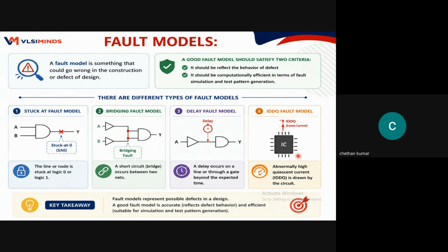IDDQ faults relate to abnormal current being drawn from the circuit; if excess current is drawn, that is related to IDDQ faults. But in our training, as well as in the industry, the main focus is on stuck-at faults and transition delay faults. By targeting these two fault models, we can say that the chips or designs will be fault free.